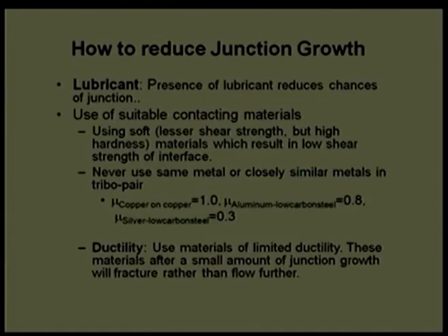Now, how to reduce the junction growth? I have noted down a few suggestions. Not necessarily everything will work in one situation, but one of the suggestions will work to reduce the junction growth. If you really want to reduce the junction growth, do not think about dry lubrication. Provide some sort of lubricant, either powder lubrication, solid lubrication, semi-solid lubrication or liquid lubrication, which reduces the interface shear strength between two